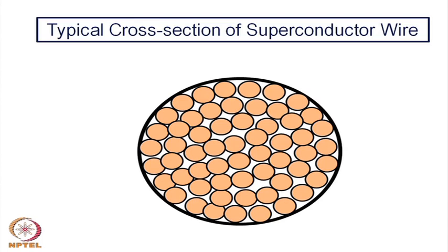That is one of the disadvantages one can say, but it is not very costly; depending on the application area, it is certainly affordable. So, all superconductors, either in the powder form or in the wire form, are embedded in a metallic matrix to avoid local hot spot generation. That is why I have shown this particular picture of a typical cable cross section, whether it is a low temperature superconductor or a high temperature superconductor.